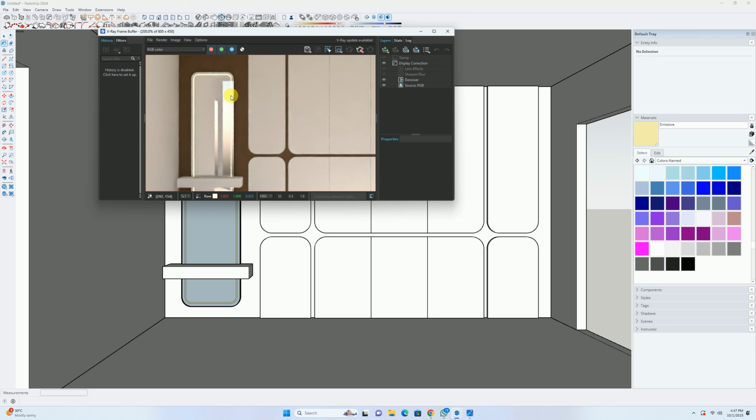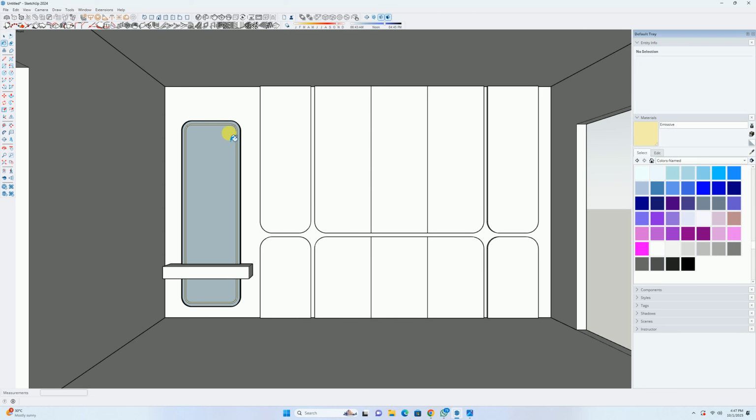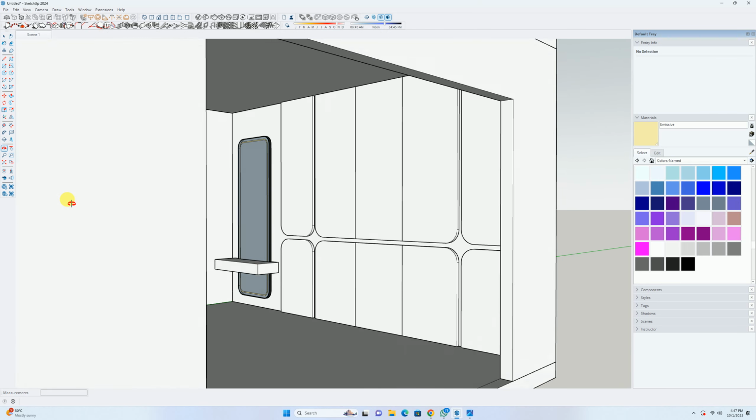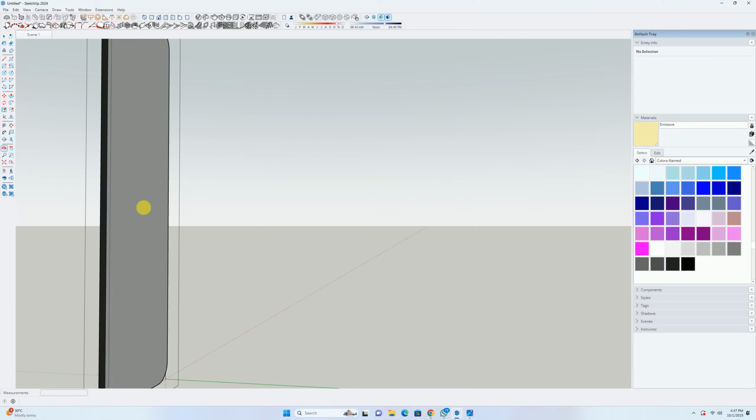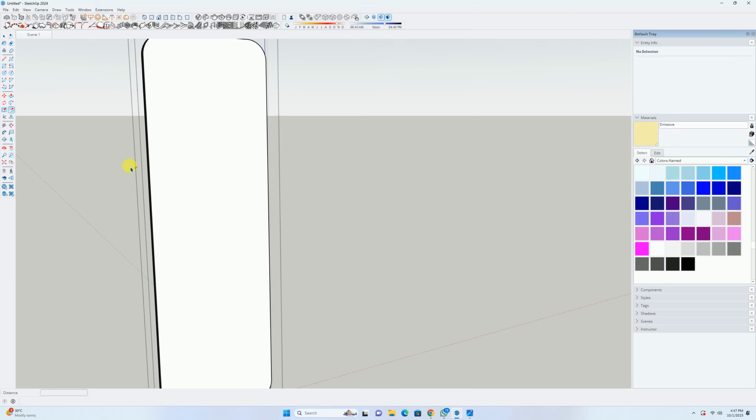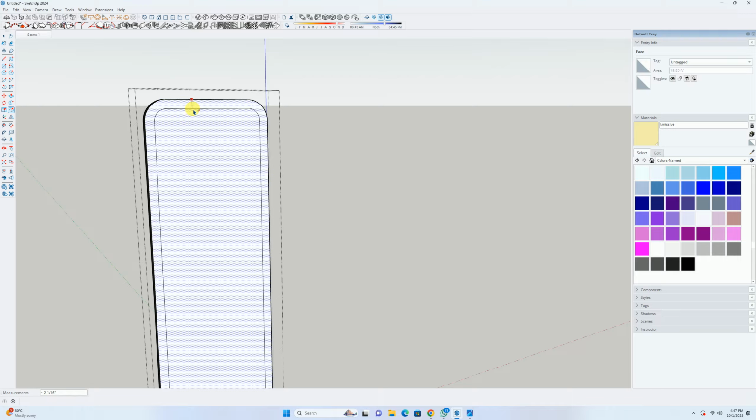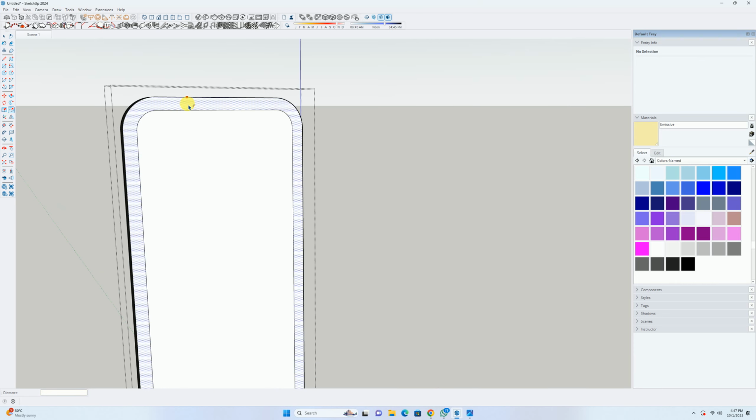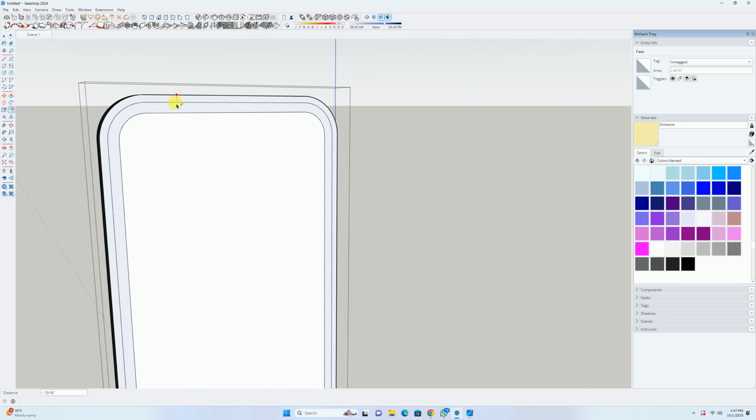Okay, I think it's quite good. So we'll stop it. Then for the back, before going to the back, what I'm going to do is I will add the scene as my animation scene, and I'll double click over here. Now we'll create a border of about 1.5 inches to 2 inches for the backlight. Then I'll create another border for the light strip as well, about half an inch.